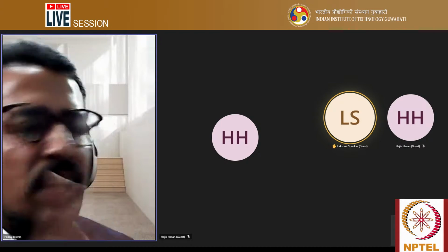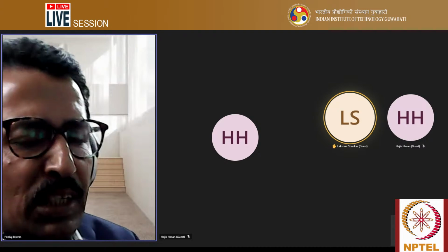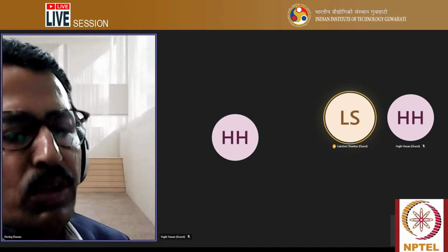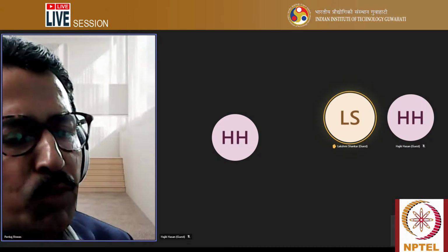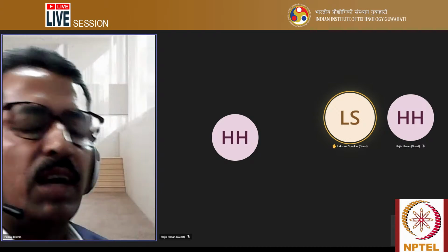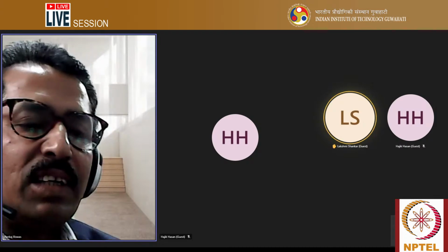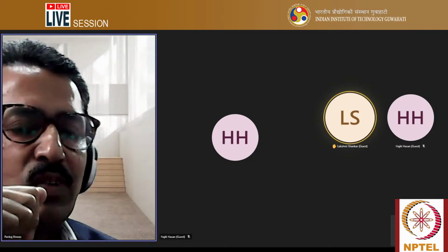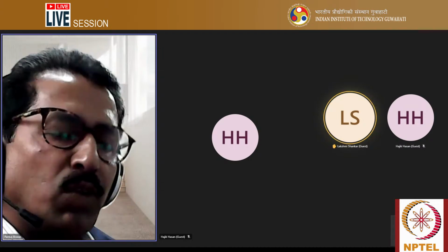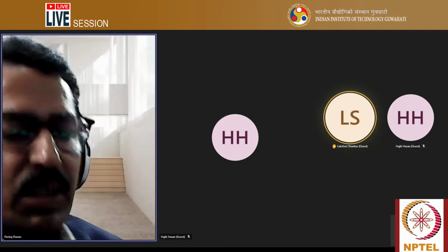I have already explained that clearly. But to mitigate these problems, some advanced types of electrode were developed. The second category I told you is rutile, which has specific features not available in cellulosic electrodes. Similarly, another category is the basic electrode. Each electrode has specific features: some can be used in the downhand position, some overhead, some horizontal or vertical.